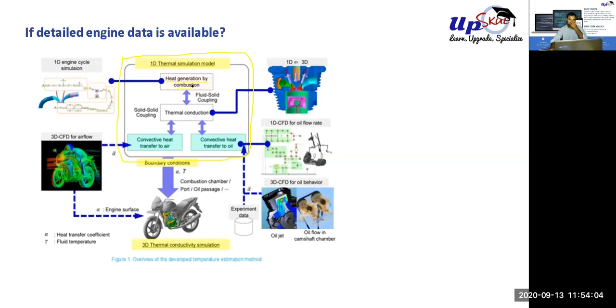We were seeing this all along. This is a 1D model of the engine, the combustion model, and it is providing the heat generated by the conversion. Then we have to consider how much of that heat is being transmitted to the coolant. That can be done with a 1D model.